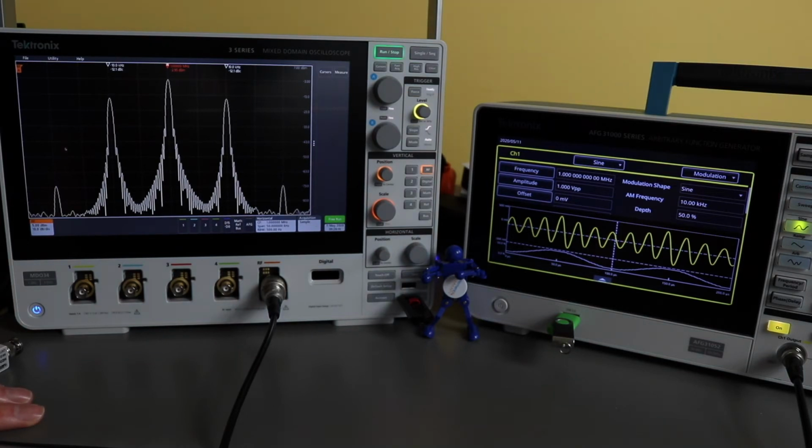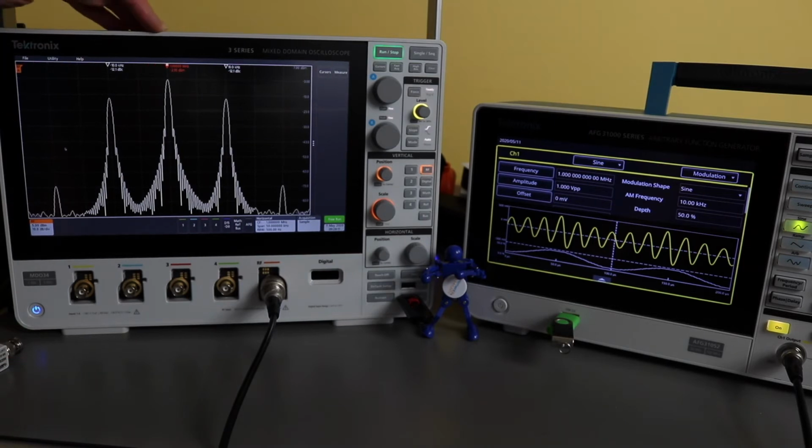So for this particular reading I've got the center frequency on minus 2.95 dBm. I've got the carriers on minus 12.1 dBc. So there's now a calculation based upon those figures that I'll need to go through on the computer, and that will give me a calculation value to compare to the actual measured value.